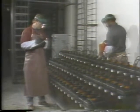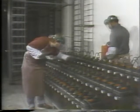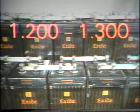The specific gravity of the electrolyte is a function of the amount of acid in the water and is a good indication of the charge on the battery. The specific gravity of the electrolyte is affected by temperature, so as we'll see, specific gravity readings must be corrected for temperature. Most storage batteries, when fully charged, have electrolyte at a specific gravity between 1.2 and 1.3.